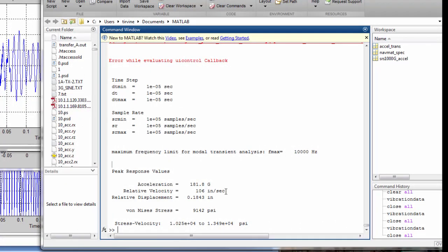Now, if you remember that MIL-STD-810E rule of thumb, for military equipment, the shock severity threshold is 100 inches per second. Well, this is bare aluminum, and bare aluminum has a shock severity of about 400 inches per second, which is about 12 dB higher than the MIL-STD threshold. The MIL-STD threshold is for military equipment, whatever that might be. But bare aluminum by itself has a higher threshold. So we're still well within the yield limit for aluminum.